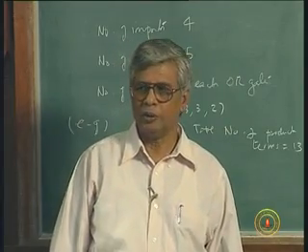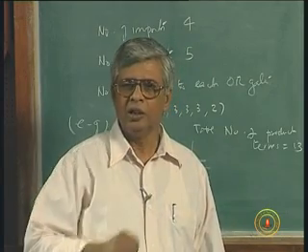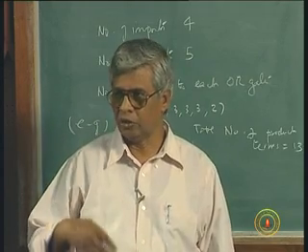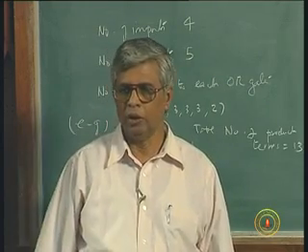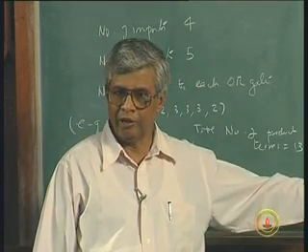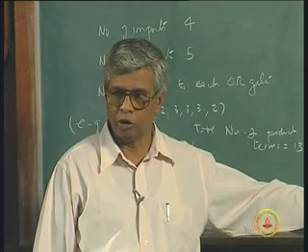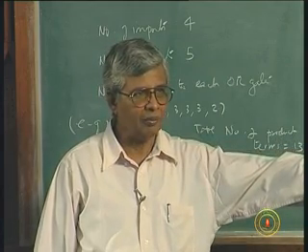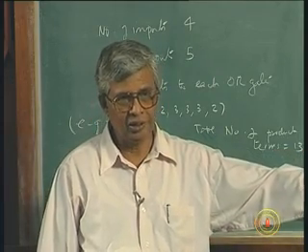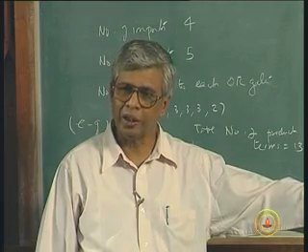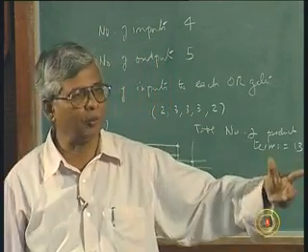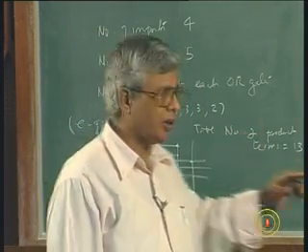The reason is, you know De Morgan's theorem and all that we have seen in simplification of logic. Sometimes it is attractive to give a solution in terms of the complement of the function, that is a simpler function compared to the true function which is more involved, or maybe the output needs to be low in order to drive a device. I am going to use F1 and F2 to drive devices which will work if the voltage is low and stop when the voltage is high. Possible? Yes, it is possible. So, in that case I would like to synthesize circuits whose outputs are low rather than high for a given combination of inputs.